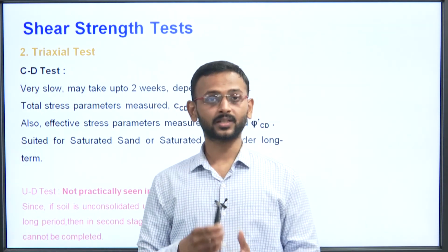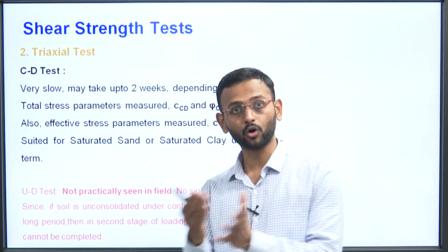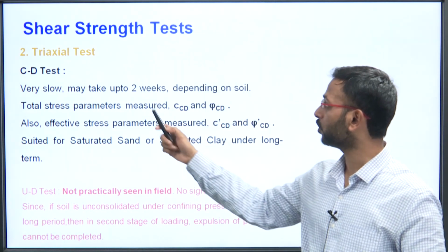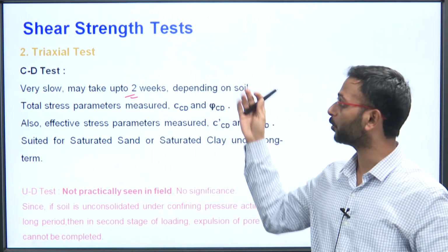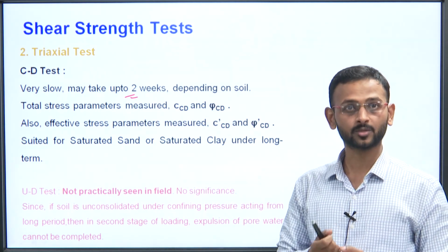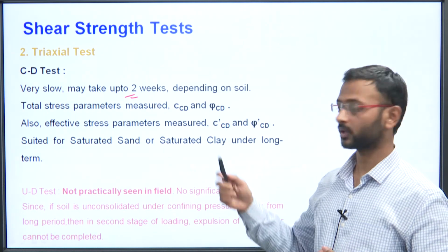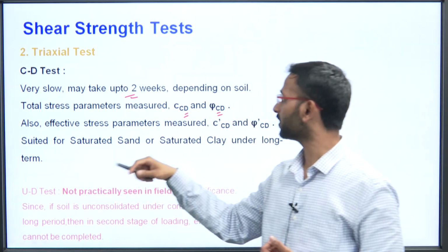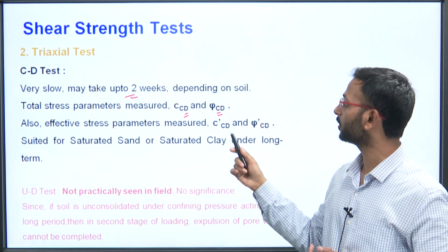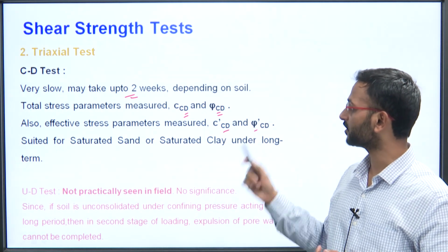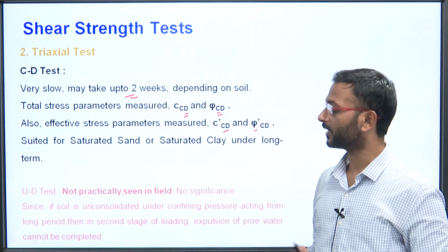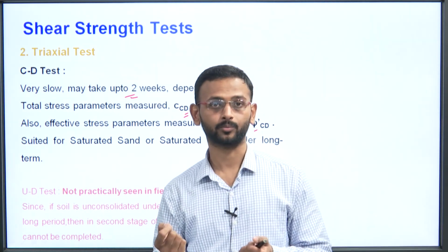So CD test will be, since you are allowing the water, that means it will take more and more time. So it is very much slow, it may take up to 2 weeks depending upon the soil. Here the total stress parameters will be measured, that is C_CD and phi_CD, okay. Effective stress parameters are also measured if you are trying to control it, then C dash and phi dash here, suited for saturated sand or saturated clay under the long term here, okay.